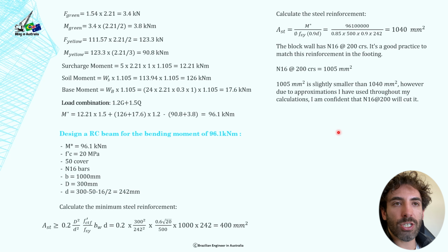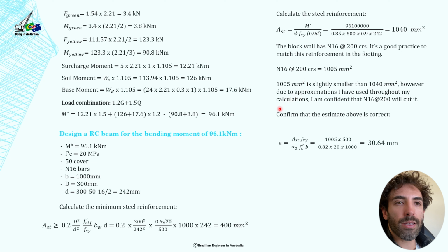And we're going to double check this right now, okay? So we're going to confirm that the estimate above is correct. Let's make sure that this N16 at 200 centers will work. If you watch my video on reinforced concrete beam design, you're going to see that we need to calculate this little a here, which is the depth of the rectangular stress block. These formulas are from your reinforced concrete classes at uni. If you remember, you've got the rectangular stress block, and these formulas are derived from that.